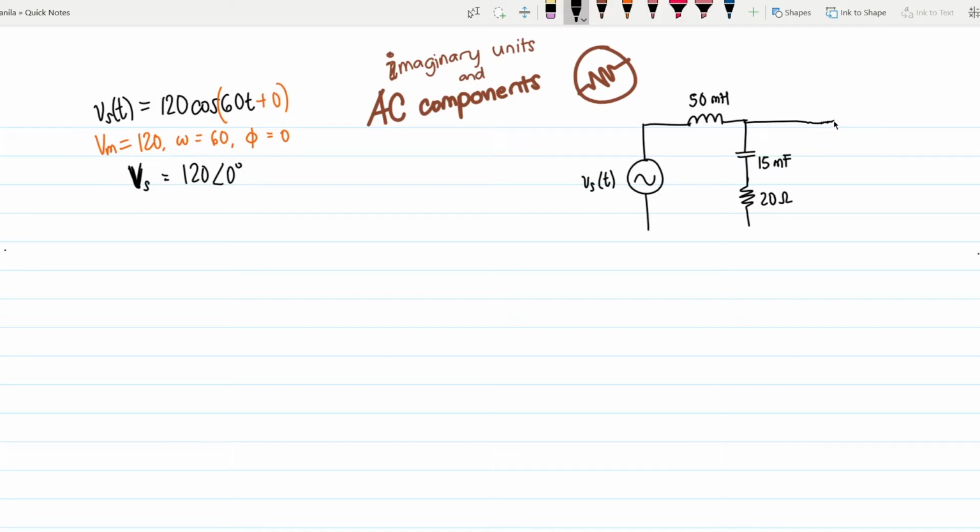And then finally, we have another branch. We have a resistor here, which is 10 ohms, and then we have an inductor here with an inductance of 30 millihenry. And so, what I just want to ask is, what's the total impedance of the whole circuit?